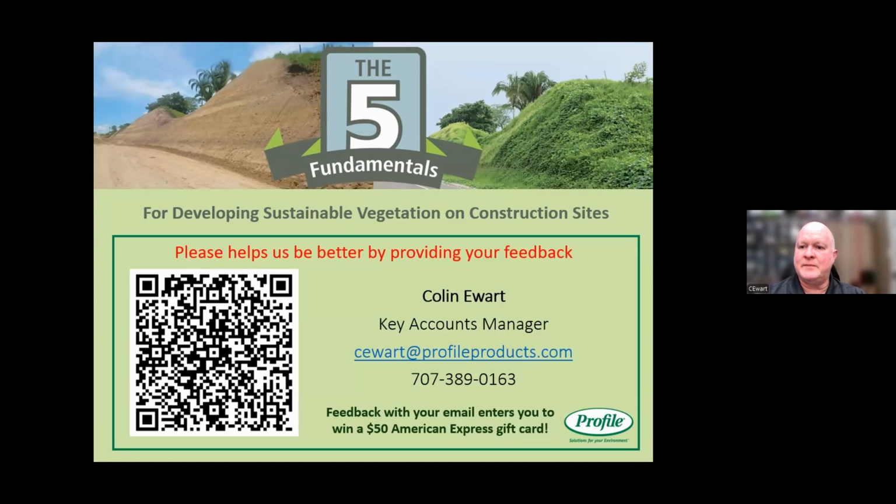That's a tough question. The answer, honestly, is not really. It does stand out. If you're talking about bonded fiber matrix, which is kind of next level down, yes, there are multiple options in the market. But on the Flexterra level, there really isn't anything in that same category. There are equivalents that can be specified. You can certainly look on QPLs or APLs in your state to see what's on the approved list, and you may find others in that category. But in terms of performance, I think that Flexterra is pretty much a standout. The reason is you get about 18 months of stabilization and erosion control. It does increase the amount of moisture retention at the seed level. And you have almost 2 years for that seed to establish itself before you start seeing degradation of the erosion control material.